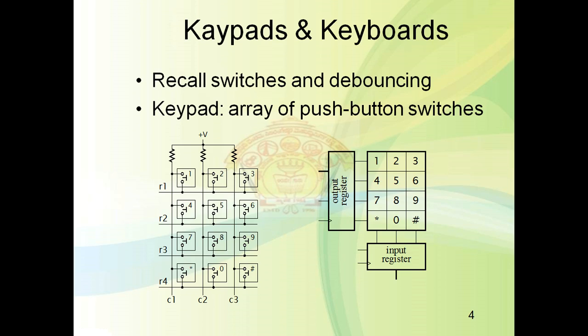The embedded software runs on the processor, and it needs to scan the matrix periodically or repeatedly. Similarly, we can detect the push button. Here there is some problem: we need to synchronize this output. One simple approach is to provide a register on the input side as well as on the output side.